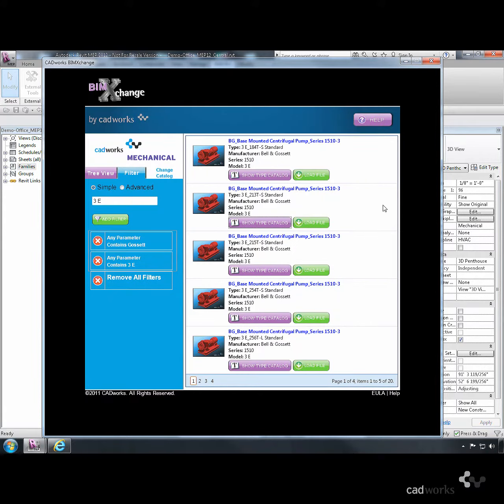Careful review of all CADworks families during content creation by professional engineers includes looking at a variety of important aspects, from file size for performance to verifying the connectors on the content are specified correctly with the appropriate parameter values mapped to them. Without the connectors on the pumps, or for that matter specifying connectors accurately, the components would not allow analysis when inserted into a mechanical system.